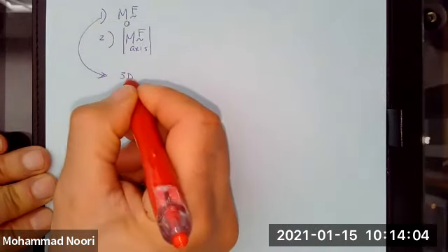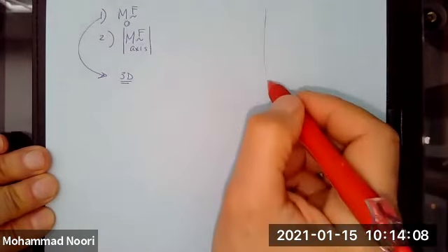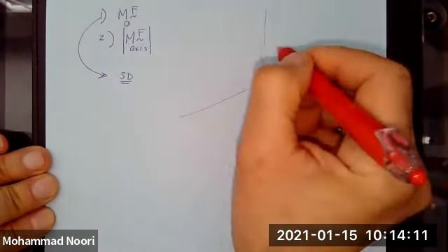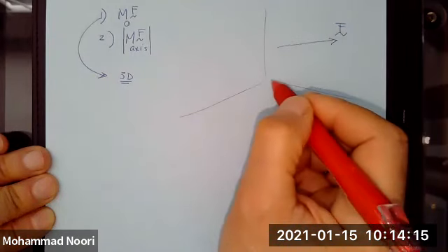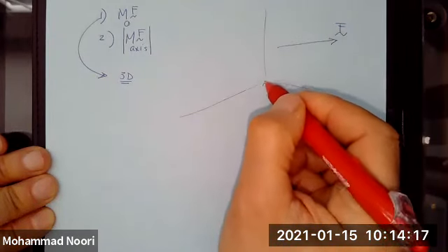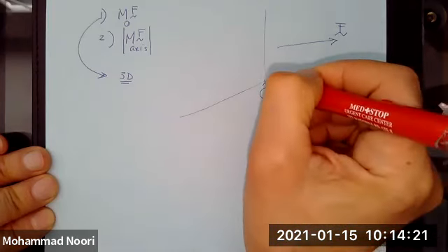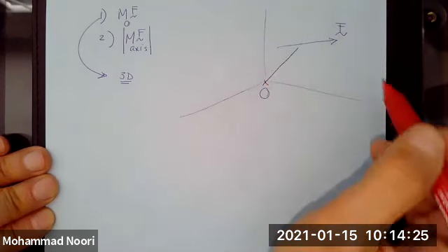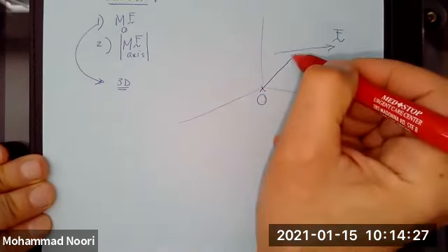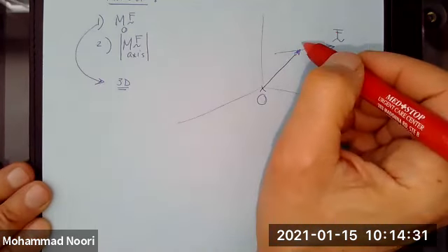In 3D, as we said, if you have a force in space and you want to find the moment of that force about an arbitrary point O, you just simply connect that point to anywhere along the direction of that force. Obviously, anywhere means to a point for which you have the coordinates, right?